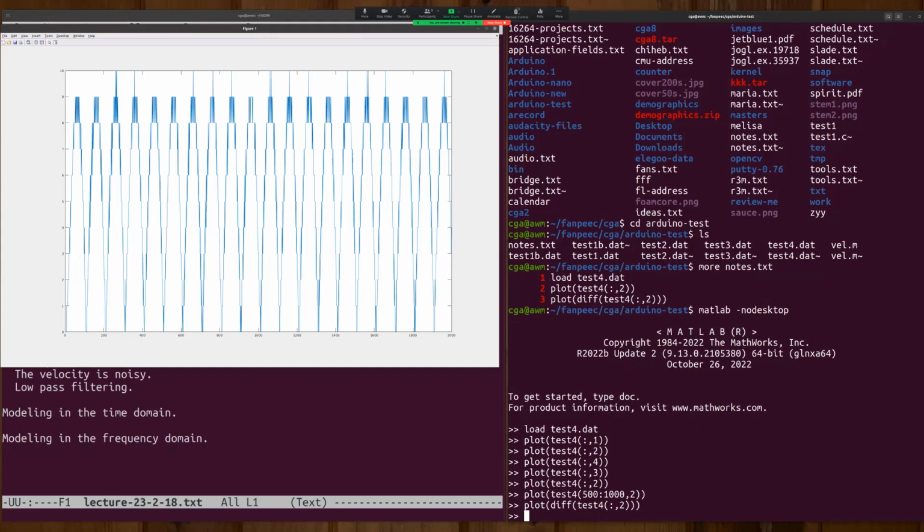Yeah, I didn't know either. So this is what I came up with. If it's moving fast, it's probably not going to change from positive to negative. So the only times when it can possibly change are when you didn't get any pulses in the last 5 milliseconds, which means the wheel either is going very slowly or not going at all.